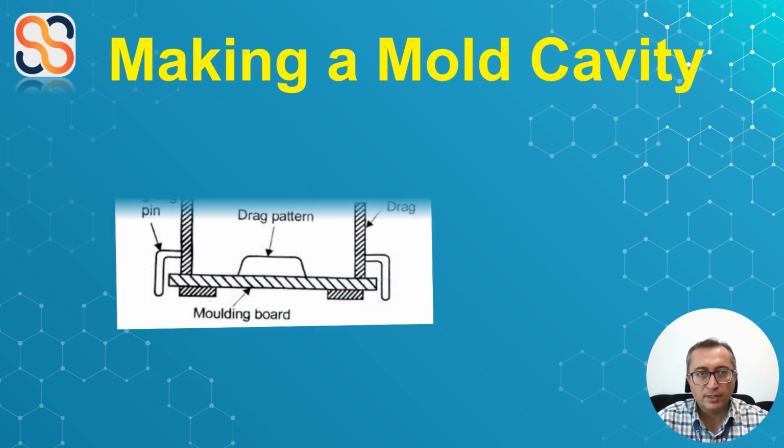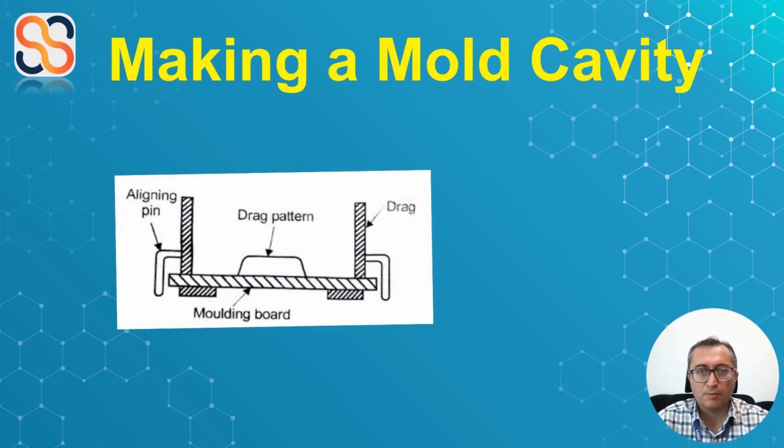Well, first off, we start by selecting a molding box of the right size to create the appropriate wall thickness for a two-piece pattern. It is really important that the molding box can accommodate the mold cavity, riser, and the gating system, which includes the sprue, runner, and gates.